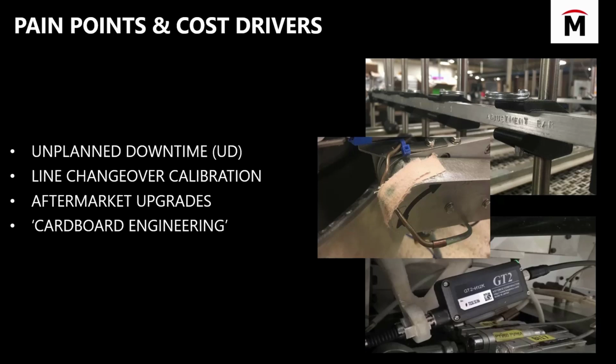It's a huge time saver when you go to reconfigure your machine in between product lines. Next is, it's a little less common, but I often see a lot of maintenance departments really hone in on this one. And it's about printing machine upgrades or retrofit brackets for an aging manufacturing machine fleet. Those guys often struggle with that, and it's a really simple fix to 3D print some brackets and holding pieces for those outdated machines.